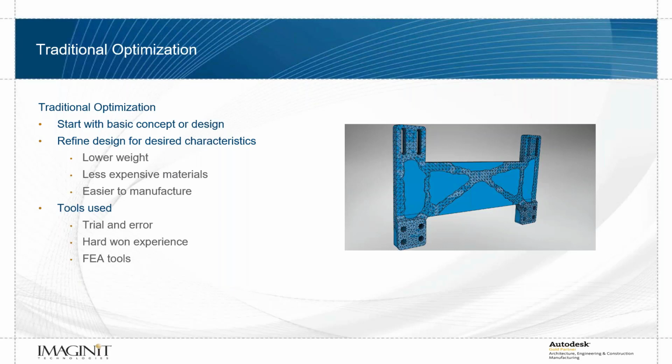And in recent years, we can optimize with FEA tools. And that's a shot from Inventor where we have the shape generator, we define constraints, we define load conditions, and we take an existing part, and Inventor can go through and begin to lay out a mesh that basically says these areas have to be here. You can begin removing some of the others so that we've got a lighter weight part, and we can work with that. So some of those tools exist in Inventor today to optimize.